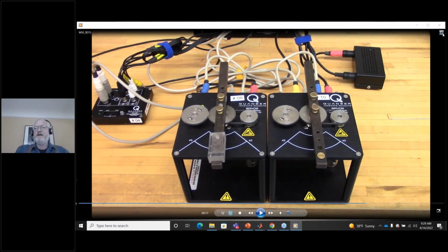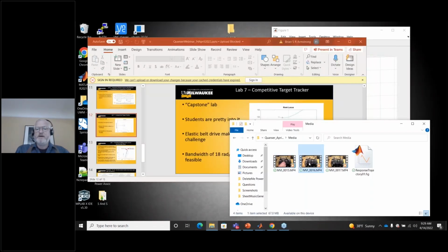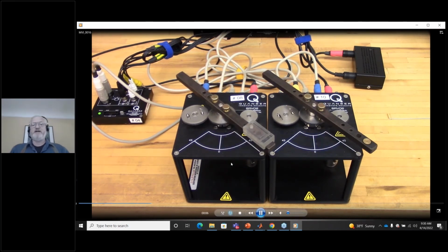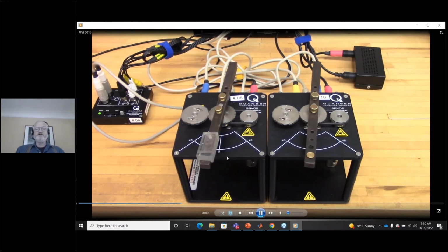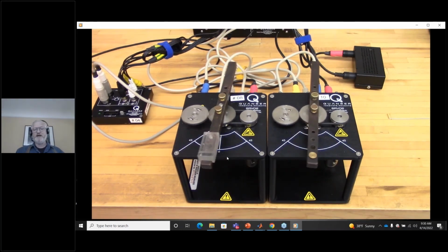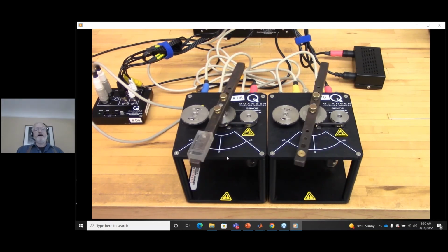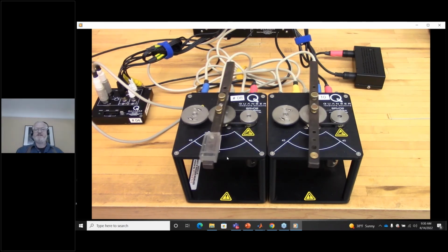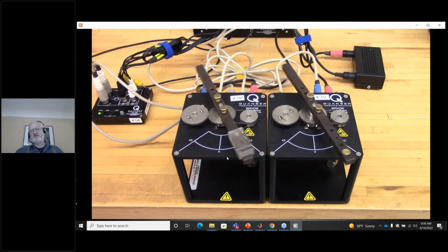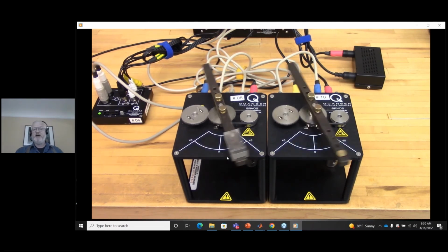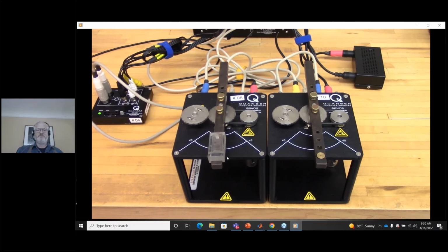Okay. And now flicking to this second video. So here it is with the trajectory being generated. It starts out rather slowly, as you can see. It's not purely a sinusoidal motion. It's this multi-sine, and furthermore, omega itself is changing over time as the unit accelerates. So you can also see friction effects, particularly on the right. And so there's a little bit of stick slip there, which will compound the challenge.